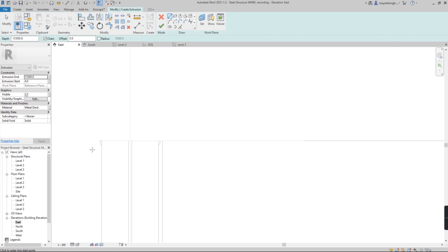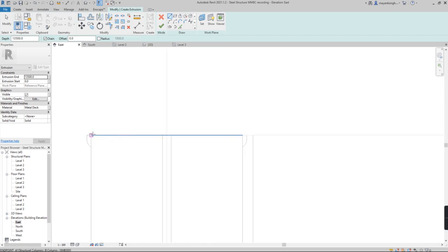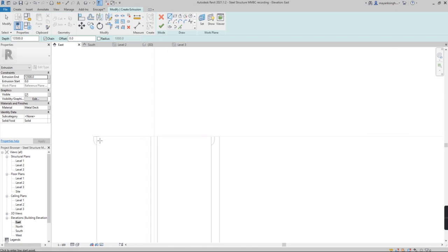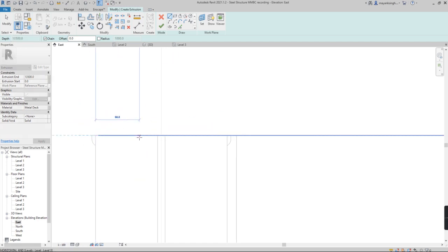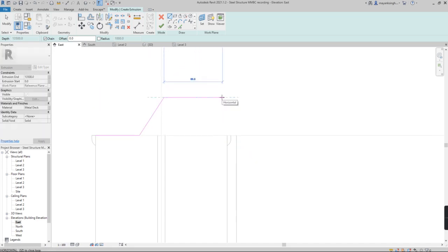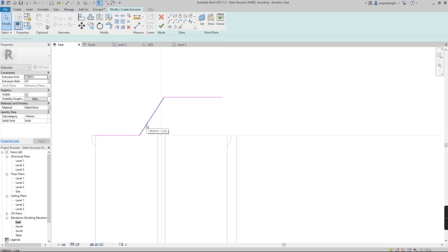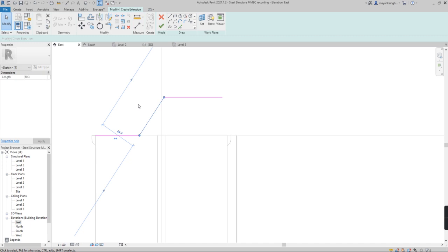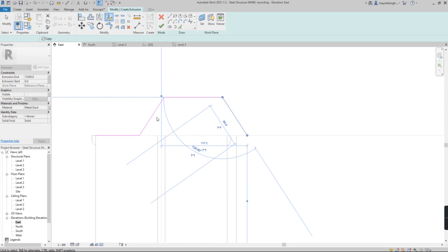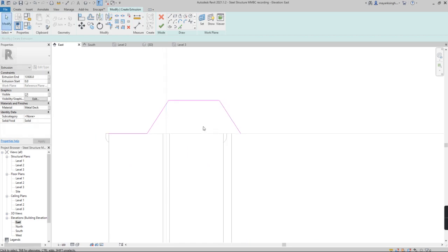Now I'm going to model one from here. Let's say 60, and somewhat let's say 60 here. Another 80, and just to check, this is 49. Let's put it at a nice 50. Okay, I'm going to mirror it using the dm command. So click here and dm, just like mi in your CAD. Click here, and now I have this, and now I'm going to replicate it.